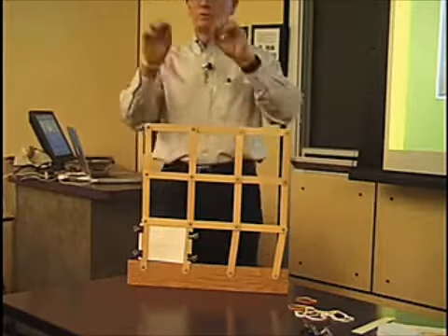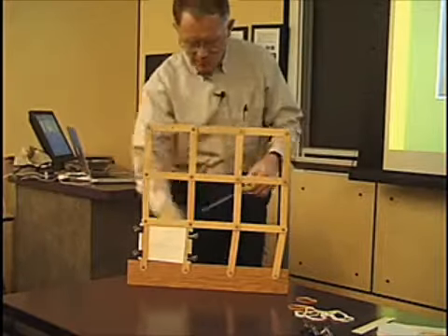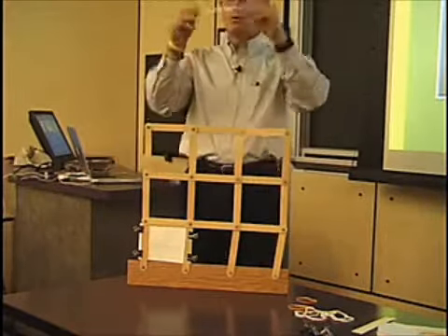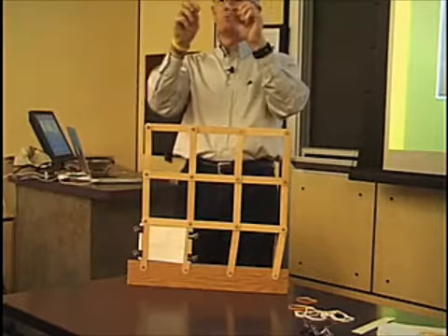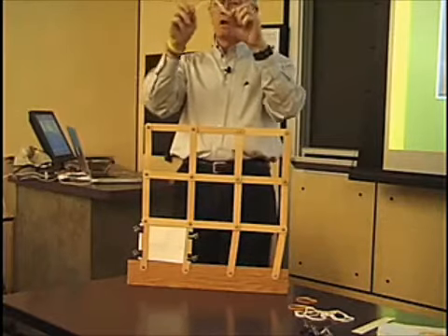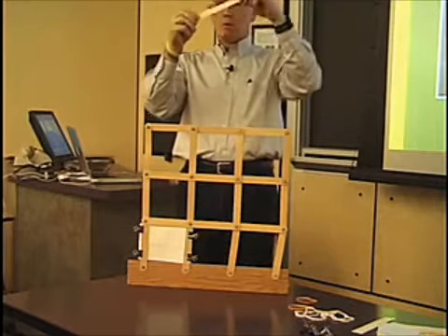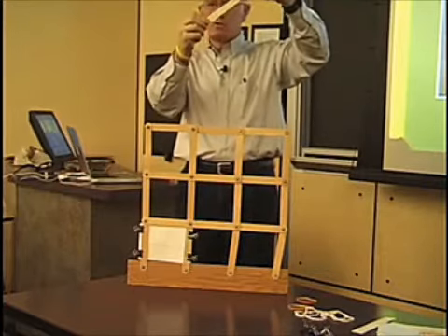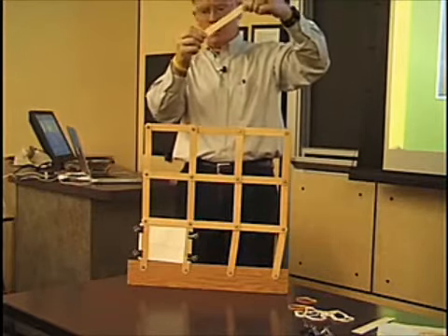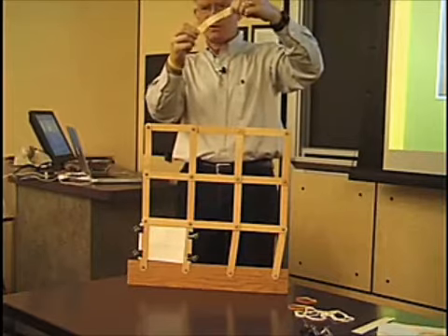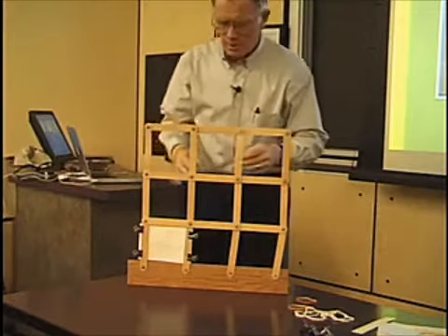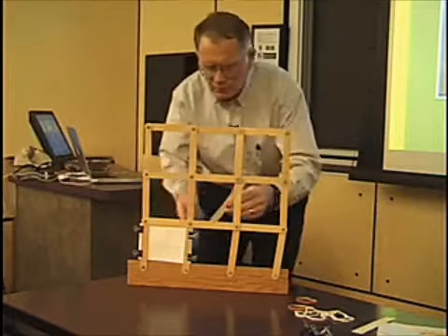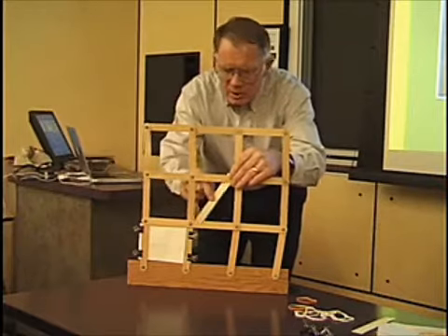So we can just take a strip of paper here. These strips have no compressional strength. I can take the ends and push them together, and of course they have no strength in that direction at all. But they do have some tensile strength. I can pull on the ends of them. And of course, if I pulled really hard, I could rip the paper, but it's got much more strength in tension than it does in compression. So now, take the strips of paper, place them on here.